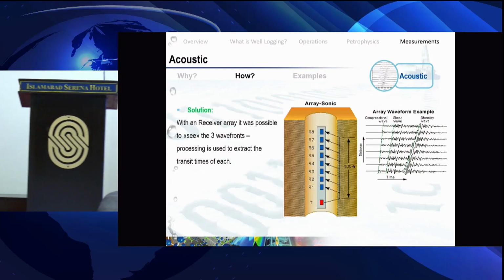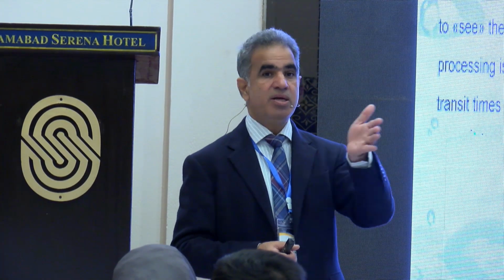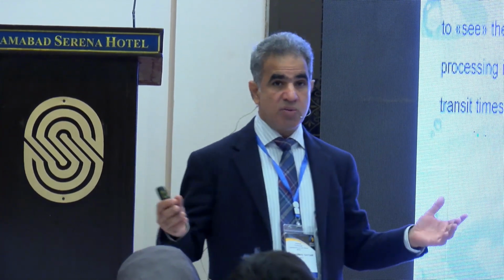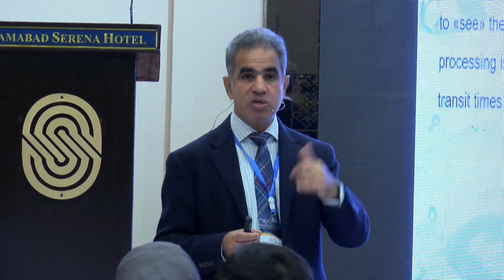So for any log we explain or interpret, we always look at the borehole information. We always have caliper data in front of us. We know the bit size the hole was drilled with, and the caliper. If the caliper reads larger than the bit size, that's washout, but breakout means the hole is ovalized. This borehole information is very critical to understanding the logs.